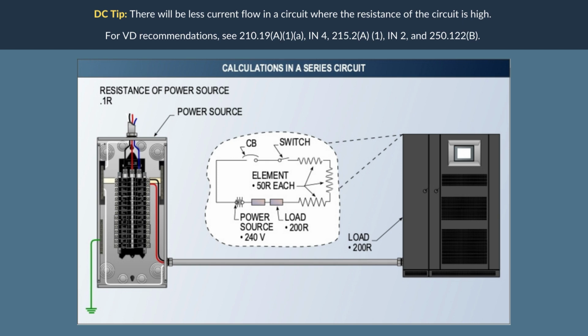For example, considering the voltage drop in the power source, what is the voltage drop across each individual load in the circuit? Use values in the illustration and text. In step 1, finding voltage drop, Vd, equals I, which is the amperage, multiplied by R, which is the ohms, or resistance. Based on the formula, Vd equals 0.6855 amps, multiplied by 50 ohms, which equals 34.275 volts. Therefore, the voltage drop in each 50 ohm load is 34.275 volts.